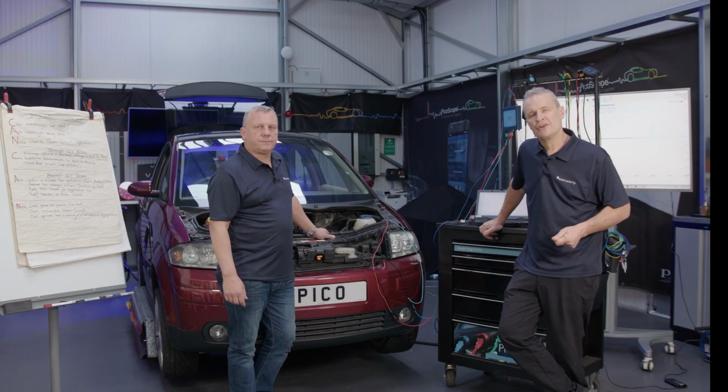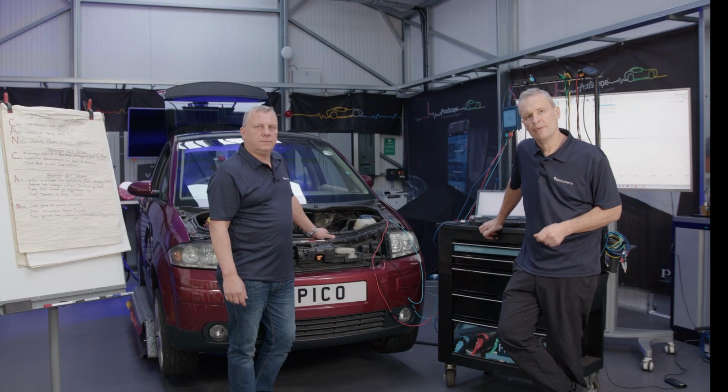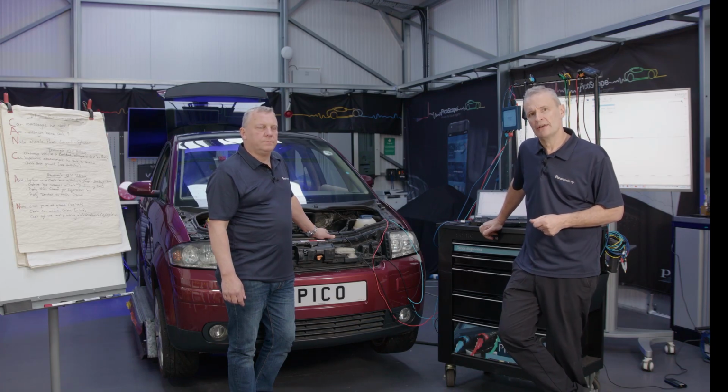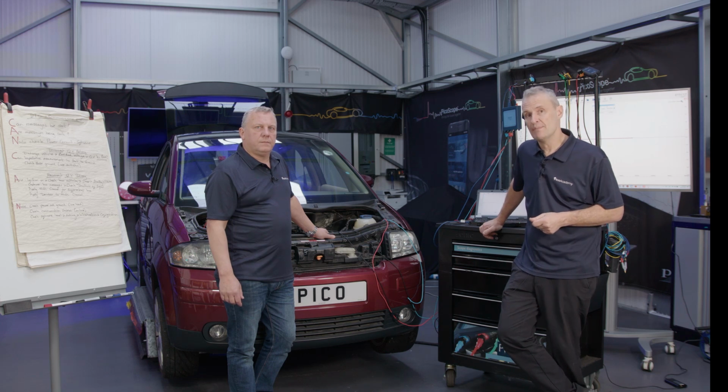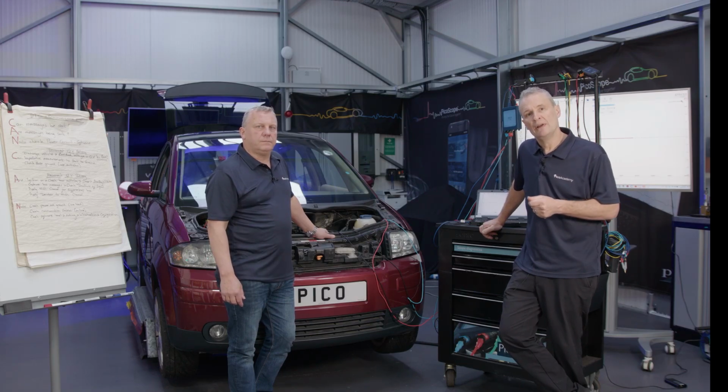We'll then move on with the CAN process. We're now going to look a little bit deeper at the CAN network. We're happy with the physical layer, the actual structure of the signal, so let's have a look at the messages in more detail. We'll go for the decoder, which introduces something called the math channel. That gives us the differential between CAN high and CAN low. We talked about differential twin wire buses in the video. We'll actually see that in action and see how we get noise cancellation.